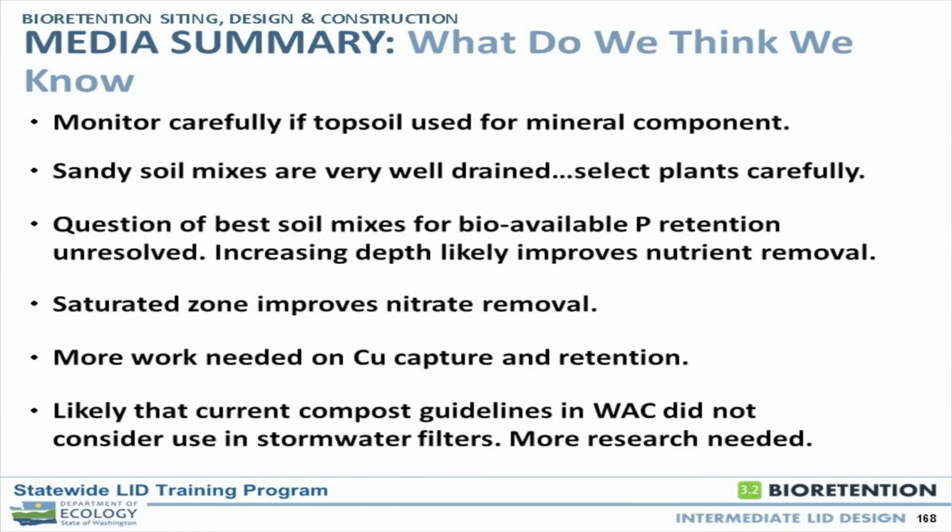And there's a whole list of criteria for compost suppliers and how they make compost. We've put those guidelines in, for example, the LID Technical Guidance Manual, as guidelines you need for your compost. Well, as it turns out, those compost guidelines are not meaningful for compost in a stormwater filter. They're great for compost for your garden, but for a stormwater filter, we are in the process now of completely rethinking the guidelines for organic material that goes into a stormwater filter.